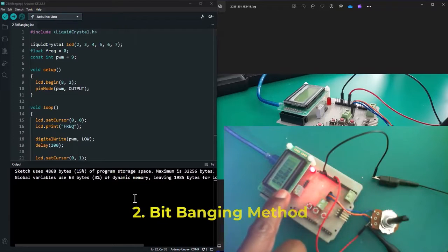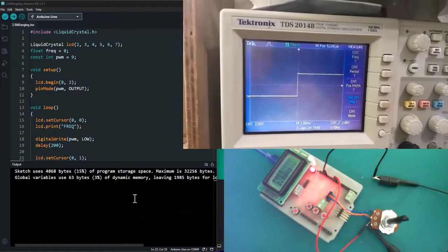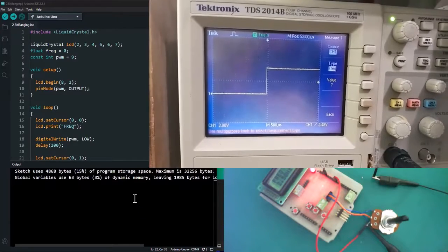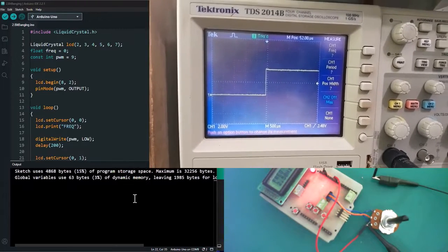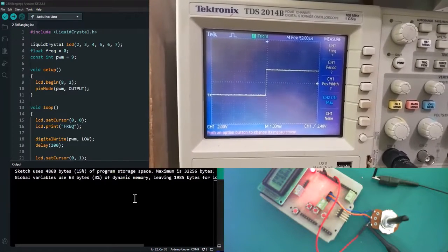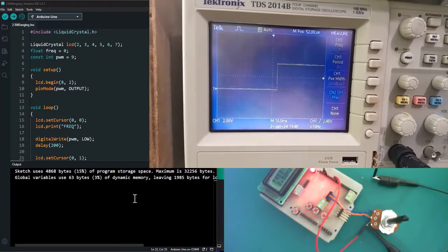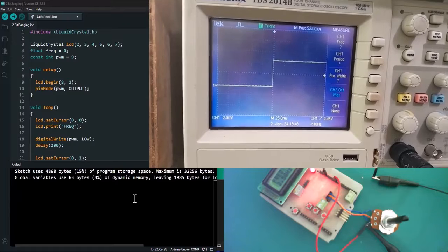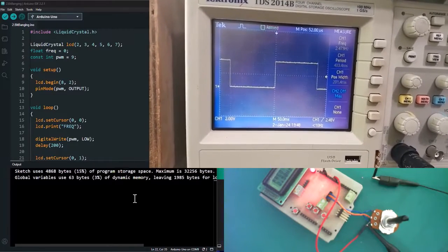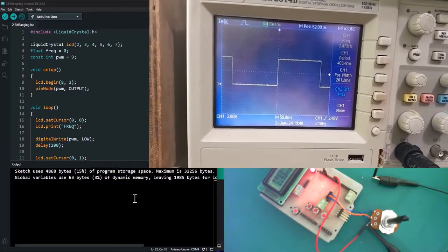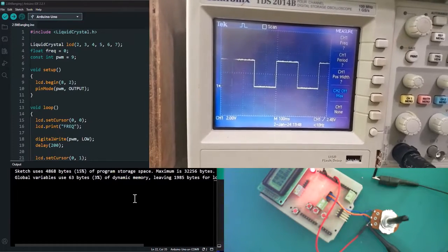displayed on our LCD display there. Now, do we have the same frequency here on the oscilloscope? All we have to do is change the time division so that we can read this very slow frequency of 2.5 Hertz that we calculated and can also see on our LCD display. There we go, it's now available. So we can see there is a frequency of